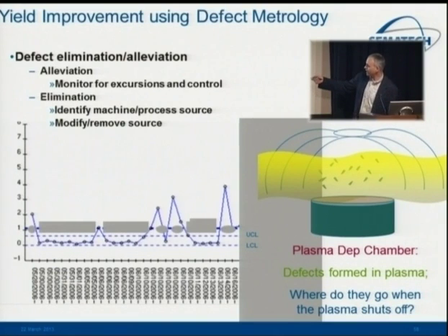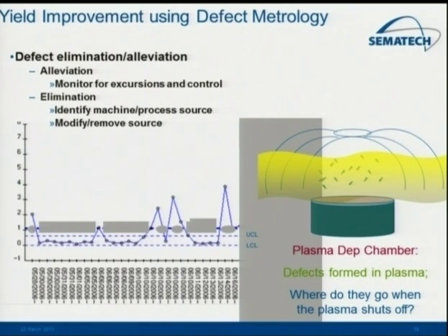If your robot scrapes against something, you're going to scrape a lot of particles onto the surface. So typically, you're not going to have 0 defects when your tool is running well. You're trying to sample that by sticking in a bare wafer every once in a while, doing a simple inspection, counting the defect density. So you may have a couple spikes here. Those are probably measurement errors more than anything, but you want to be able to detect when something starts to go out of control.